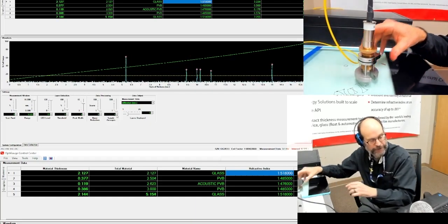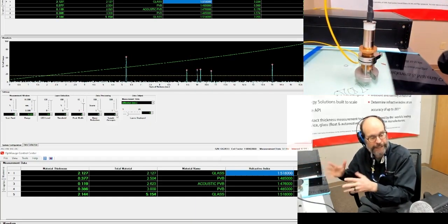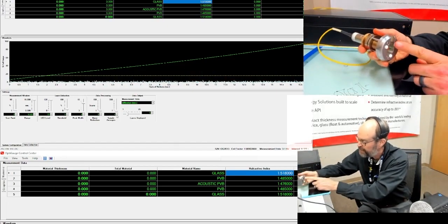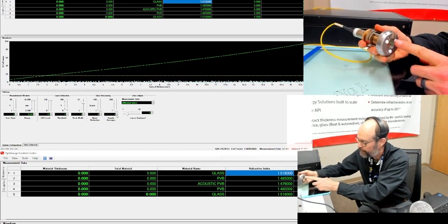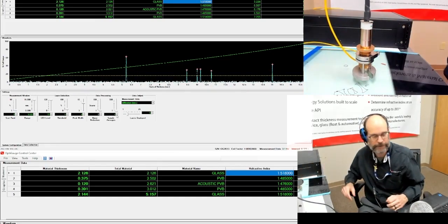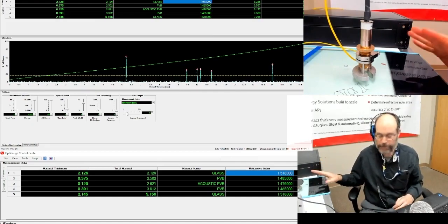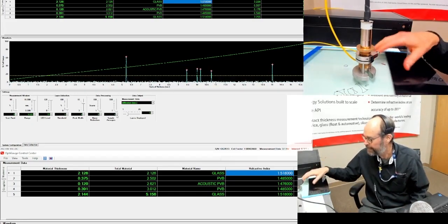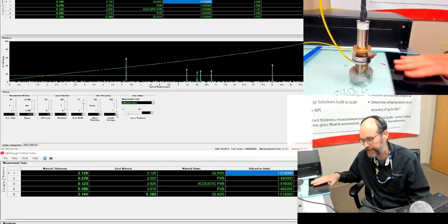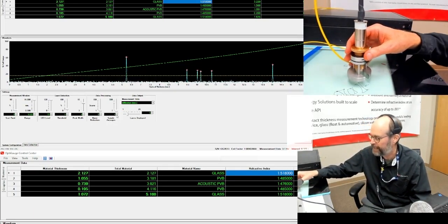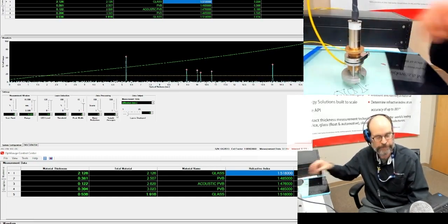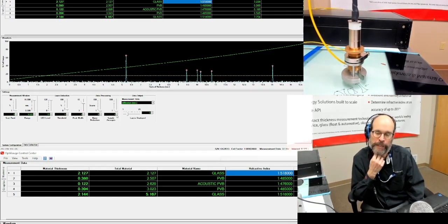Then you know you're in good shape. But if you notice that your signal is starting to degrade and you're not getting the peaks that you used to get, it might be because you're developing wear or flats on the 3 Delrin balls. They're pretty rugged, and glass should not wear them down very quickly. But if you set it on a piece of anodized aluminum over and over, eventually you're going to put a flat on those balls.